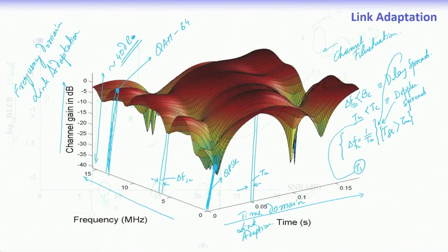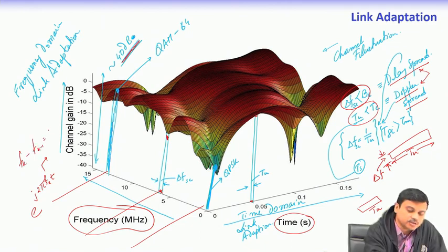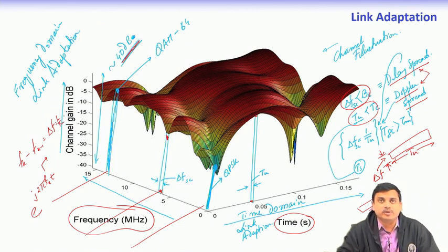And then we said further that since this fluctuates, there is around 40 dB of fluctuation of signal strength. Since these subcarriers are different subcarriers, they are all orthogonal. So, we remember that they are all orthogonal subcarriers, e to the power of j 2 pi f k t, and the f k's are chosen such that f k minus f k minus 1 is equal to delta f, which is equal to 1 by T u. This is the condition we have been using.